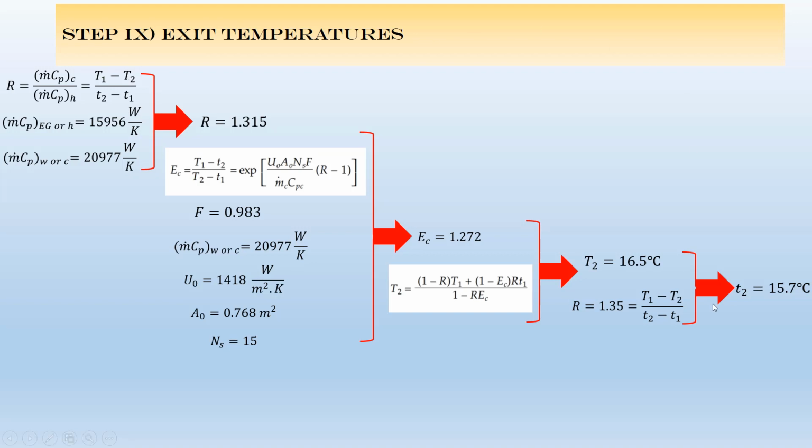So look, guys, now you found the exit temperatures. Now you need to check your assumption. If you use any of those three methods, you will see that the new average temperature, using the exit temperature for the hot fluid and the exit temperature for the cold fluid, is less than 15 centigrade.